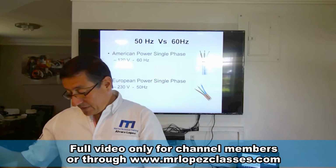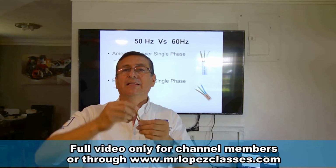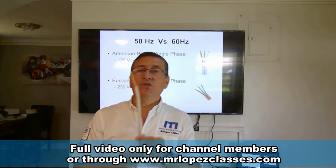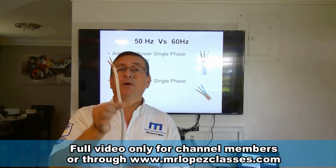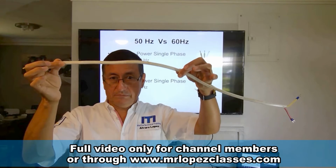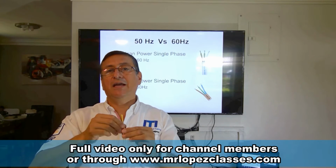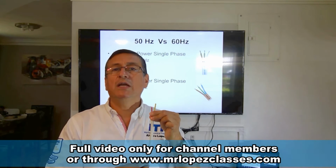What is the difference? The American wires are stranded wires, and they are elastic, not rigid like the wires used in construction. They are not approved for marine application. In marine application, you need marine grade cables. The marine grade cables are not corroded. They are flexible, and they have a higher capacity to resist high temperatures in the engine room,